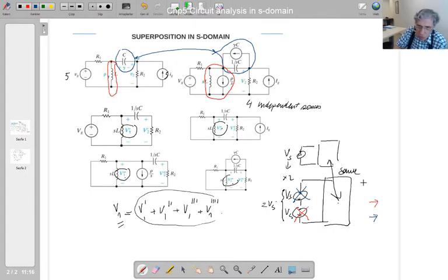These two solutions are going to be the same, because if you remove one of the independent sources, you get this. So according to the superposition theorem, the addition of those two is the 2 times Vs solution, isn't it? So for the elements within this circuit, the currents and voltages you found multiplied by 2 give you this circuit's analysis result.